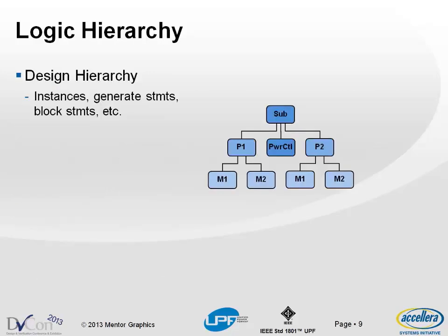We think in terms of the logic hierarchy in the HDL design, because in UPF we're specifying power intent for your design, and we have to apply it to the structure of the design, which is typically a design hierarchy or a number of modules instantiated in each other, etc. The term design hierarchy in the HDL context encompasses a lot of things.